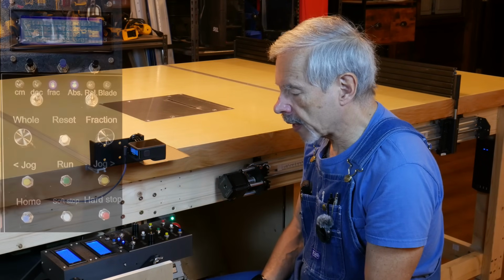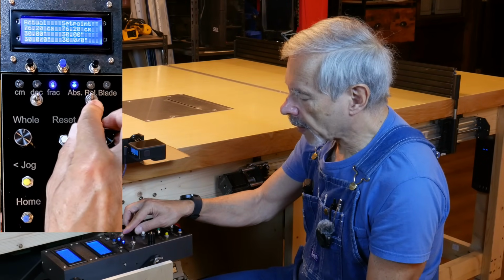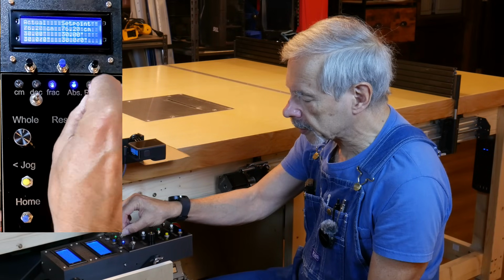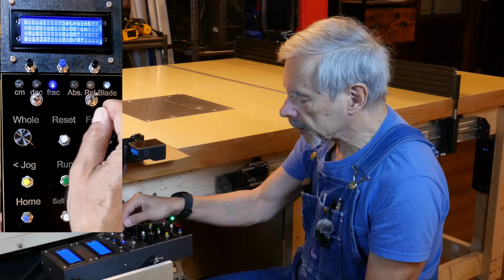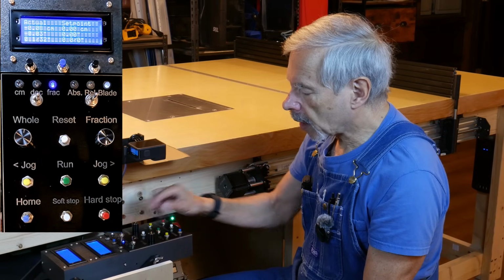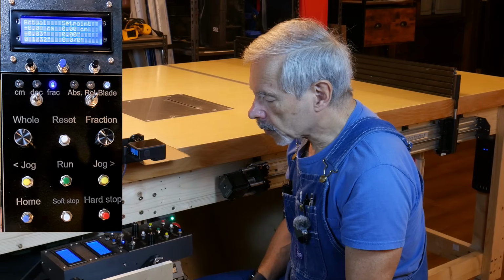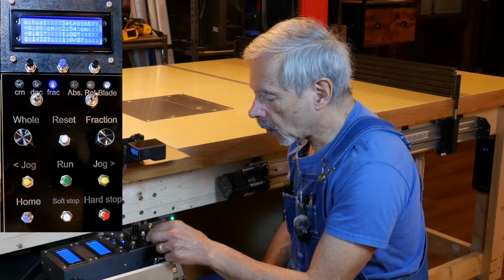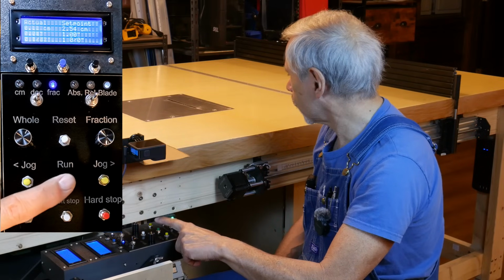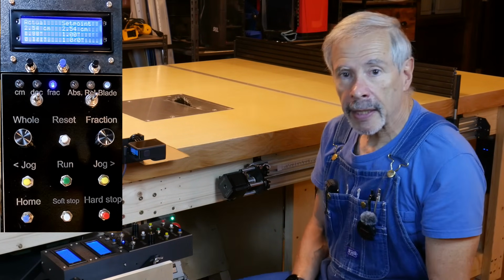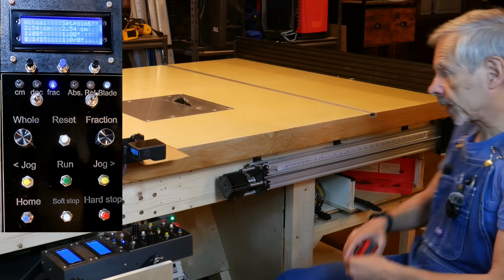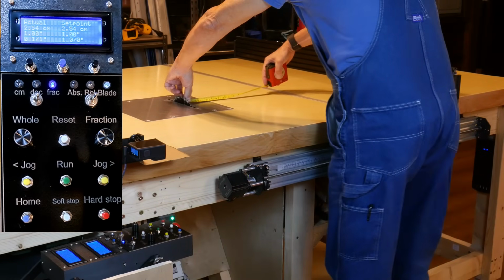And to verify that, I have to do one other step, and that is I'll use this here 3-position switch. For now I'm only mentioning the 3rd position, which lights up the blade LED, and that means I'm now going to control the blade. To control the blade, I'll just go and tell the blade to extend by 1 inch. And so there is that. Now I can measure the distance between the blade and the fence.